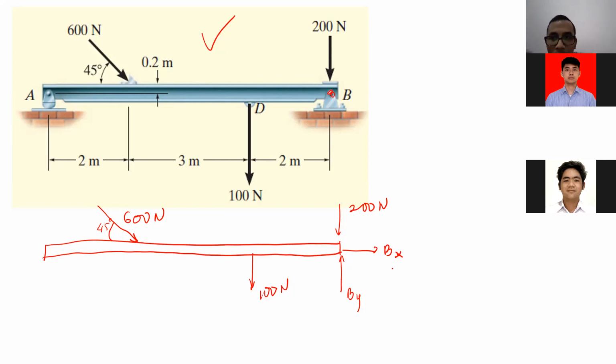Okay, Alberto. Now, because just now you asked me, try to draw the reaction force at point A, because of the roller at point A. I want to replace the roller with a reaction force. What am I supposed to draw there? AX and AY. Now, okay, let's retract a bit. Point A is a roller joint, right? We talked about it, right, Alberto?